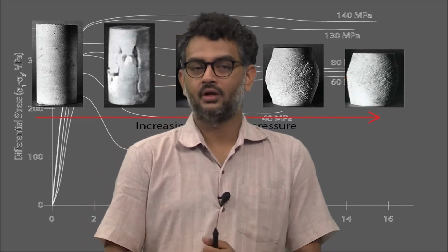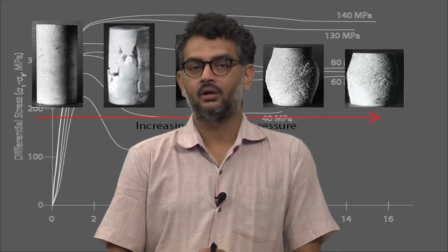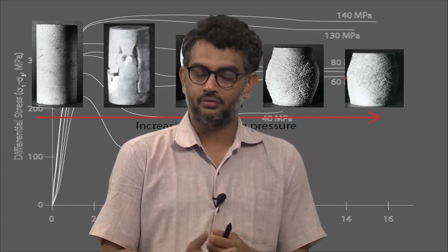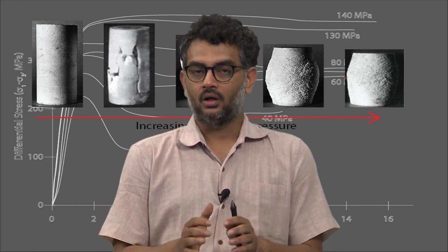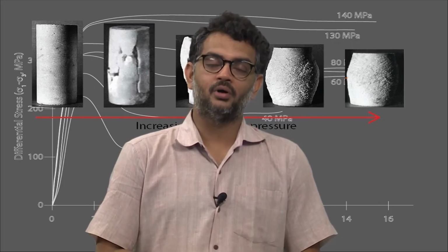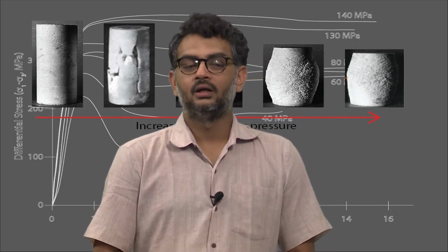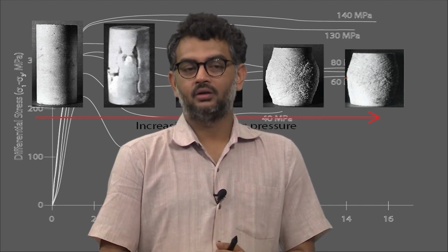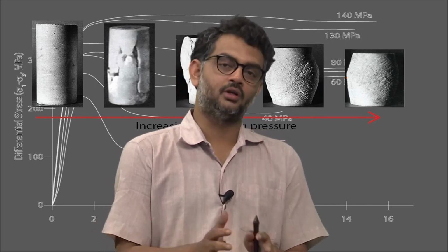So, the pore pressure has a very important role in determining the strength and flow of the rocks in general, because if I have a rock at say 20 megapascal confining pressure, then if I add pore pressure to the rock, the effective confining pressure reduces.